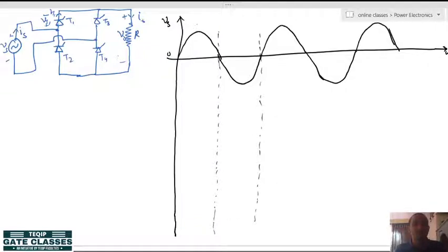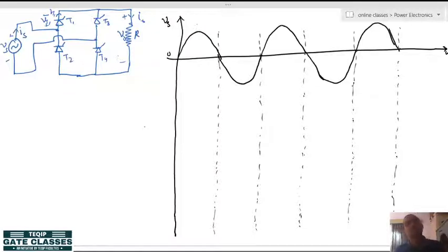Previously, before the advent of thyristors, we were using thyratron tubes, and with that to some extent we were able to control the phase, but not to a great extent, alright. But here we can very smoothly control the phase. Even if you want to control the phase in decimals of a degree, let us say 0.1 degree, 0.2 degree, that is also possible with these circuits with the advent of thyristors, alright. And ultimately you are able to control the average value. Before thyristors or thyratron tubes, the only way to control the average output voltage was to step up or step down through controlling the amplitude of the wave, which requires the use of transformers, alright. But that was a very costly and very heavy affair, and also had limitations.